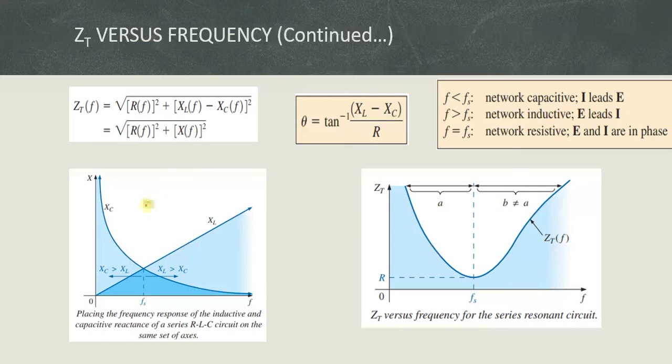Okay, so this is the hyperbolic equation, and it is due to the capacitive element, and this is the element which represents the response of the inductive element. If I combine these, this is my overall response. Just see it. So this is the overall response, which I have drawn here. At which point both curves intersect, that corresponding point is called the resonance condition.